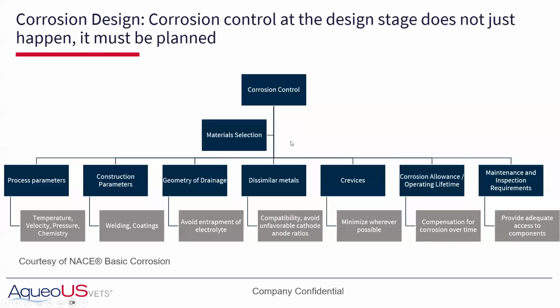Something no one wants to think about, but you need to, is corrosion. Obviously, these vessels are going to be out in some cases in outdoor locations. Obviously, there's water flowing through them. Some of these waters can be a bit corrosive. Some of the most corrosive waters that we're seeing are some of the cleanest ones. Some of the groundwaters don't have a lot of mineral in them, just a little bit of PFAS from a spill or something. Those things can have a tendency to be pretty corrosive. So it's something you need to think about.